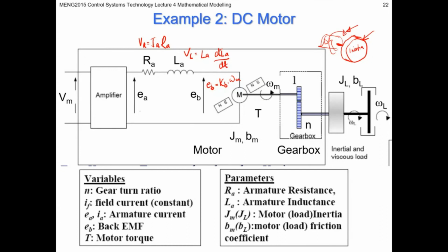It has an inertia of its own. So we have to accelerate the combined inertia of both of these. We have to take into account the gear ratio between the two as well, but if we do that, you can see that this isn't changing, this is constant, so they're rigidly connected.